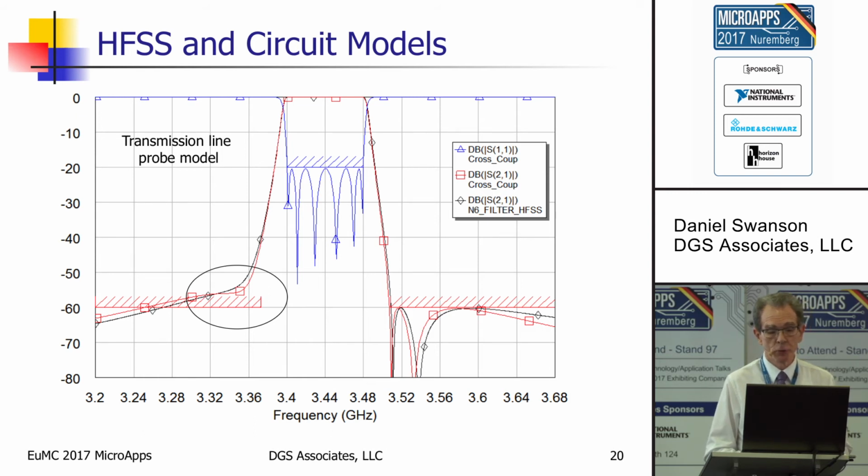I can actually tune the circuit model so that the zeros line up exactly, but then this peak will drop down. The peaks won't match the goal. So you can either make the peaks match the goal, or you can make the 0 frequencies line up exactly, but you can't get both. But this is 60 dB down anyway.